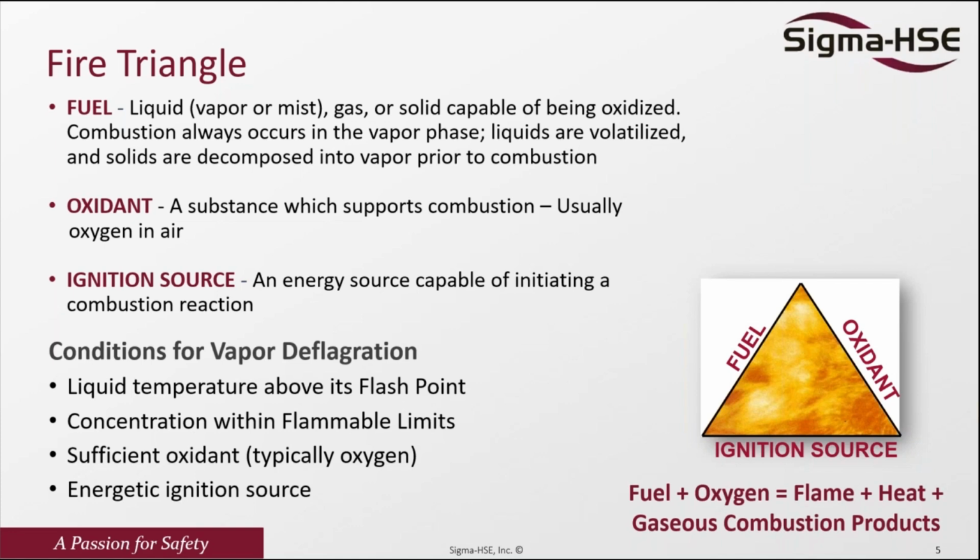And to have a vapor sufficient enough to sustain flame combustion is termed the flash point. So we need to understand the flash point of this material. After knowing the flash point, we need to also know the concentration. I will dive into that very soon. We need to know the concentration, which is the lower and the upper flammability limit. We need to also know whether we have sufficient oxygen to sustain this combustion, and we need an initiator, which is the ignition source. So that is for solvent.